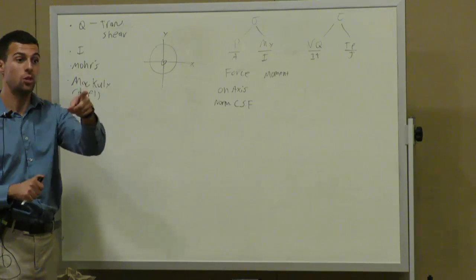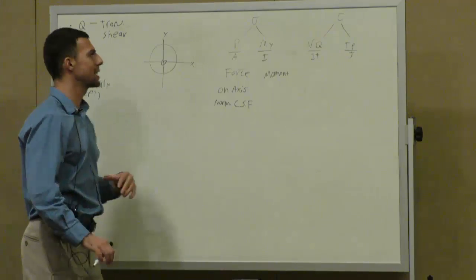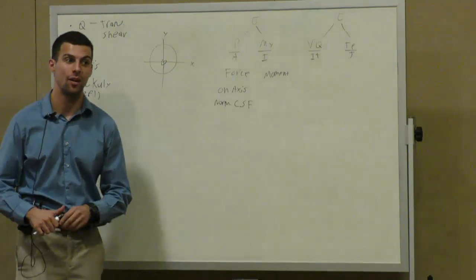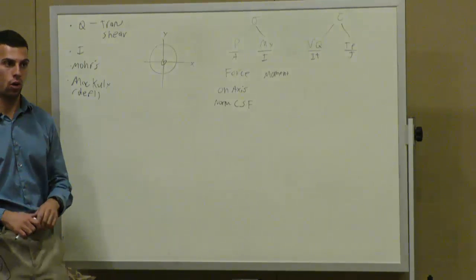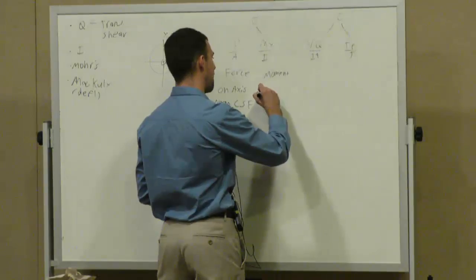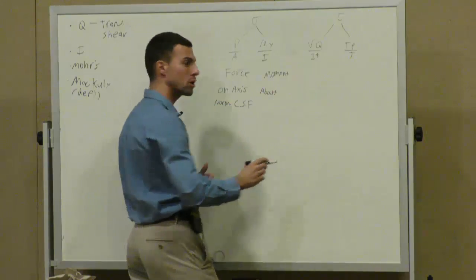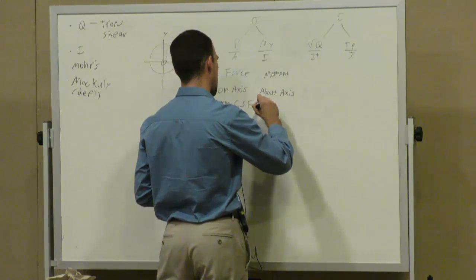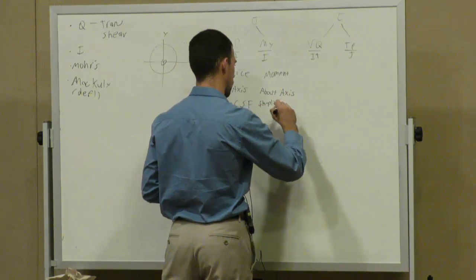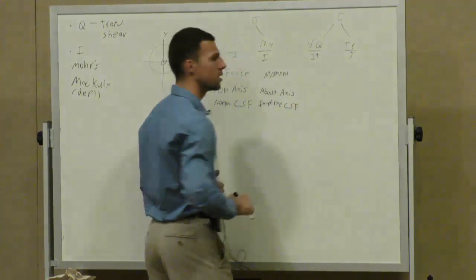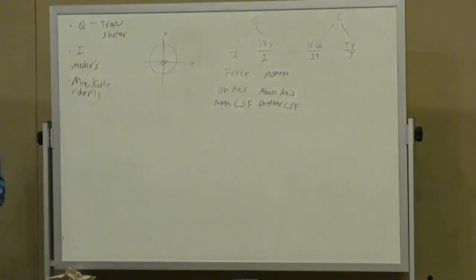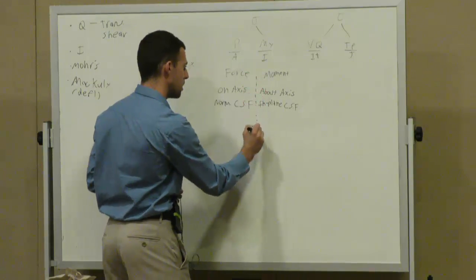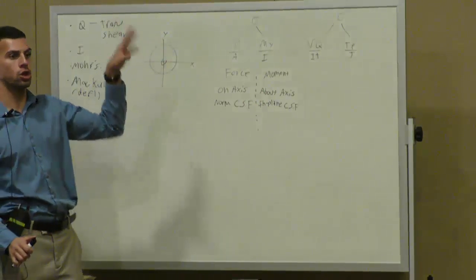X or y, right? Those ones we can say are parallel or in plane with, which is kind of a better way of saying it, right? In plane with the cross-sectional face. So there's a moment that is about, notice not on, but about an axis, any axis that is in plane with the cross-sectional face. Okay? So those are the two load conditions, let me draw a line between them, that can cause normal stress.